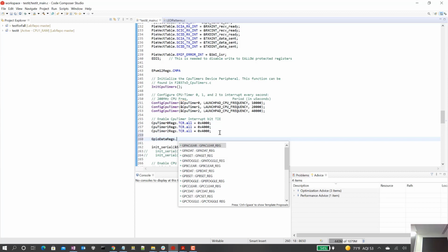So remember that. You see, this is a beautiful thing about Code Composer. One thing, of course, you got to figure out what the name is. Well, where do you find that? Go look in other example code. Go look in that ledpatterns.c or whatever. Remind yourself. Always remember, and these are great things for the how-to document too, but always kind of be reminding yourself with example code. Don't think you have to figure it out without example code. Go back to the code you wrote. And remember, you know, all your projects are going to be over here in the left. So go back to lab 2 and remind yourself, oh, that's how I turned on and off that LED, right? Type of thing. Okay? Don't forget that. Don't forget to go back and look.